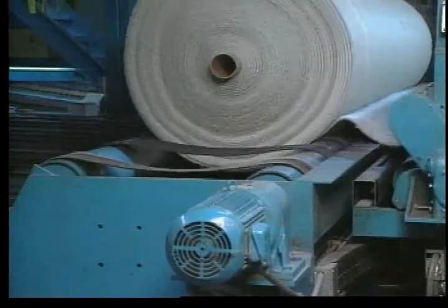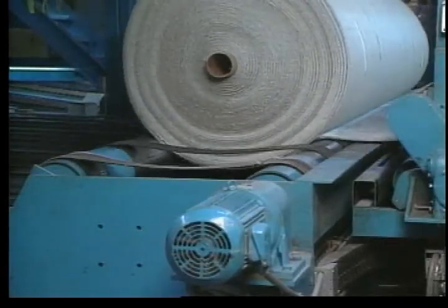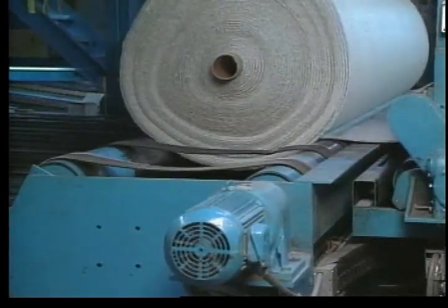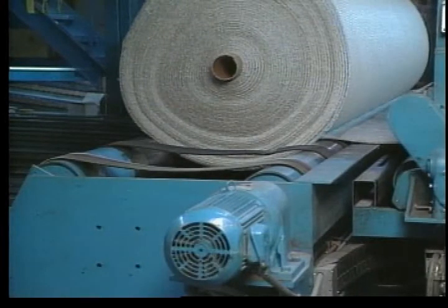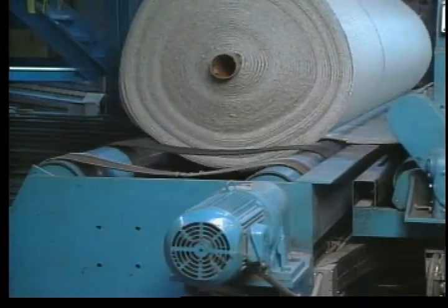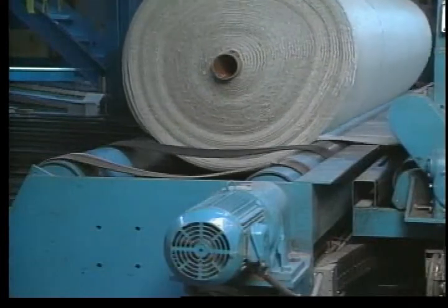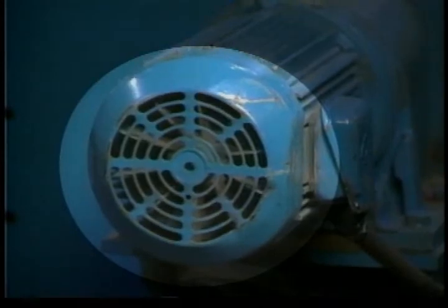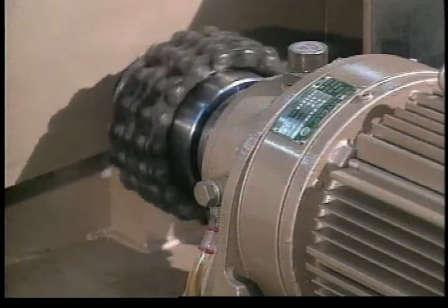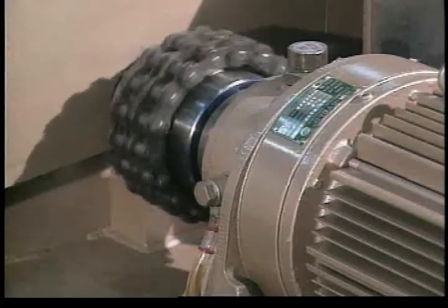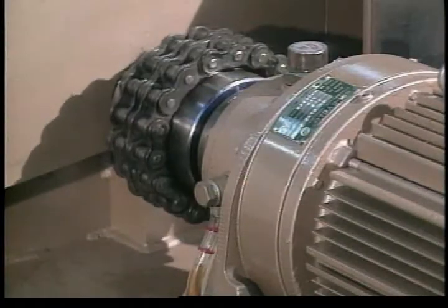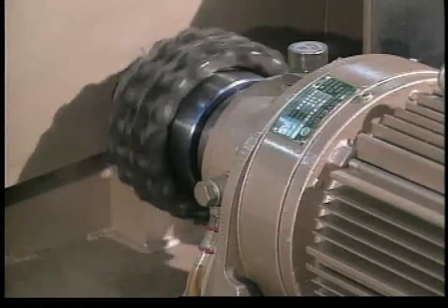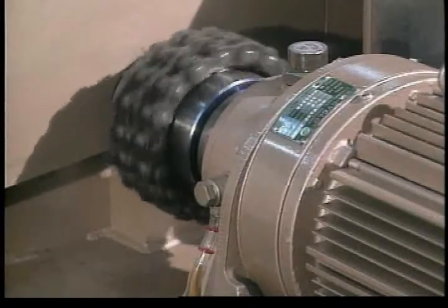Sometimes the size of the load may be a source of problems. When very heavy loads must be started or accelerated, most inverters can be programmed to provide a torque boost, a surge of voltage that momentarily increases torque. However, these boosts generate excess heat. To avoid damaging the motor, torque boosts should not be used routinely unless some provision has been made for removing the excess heat from the motor. Loads may also be a source of problems when inverters provide braking. After the inverter cuts power to the stator, the rotor continues to turn because of the momentum of the load.